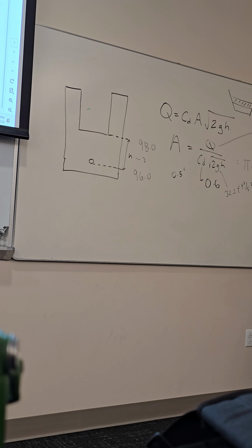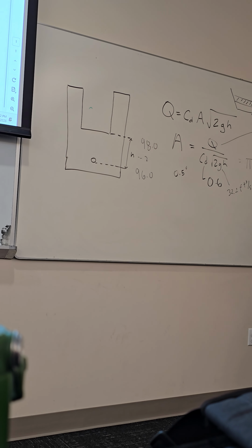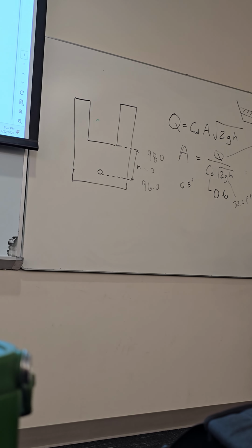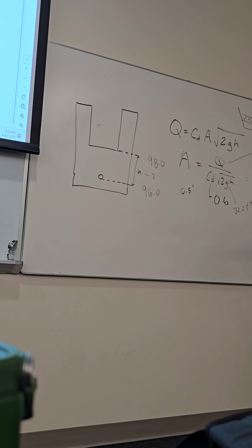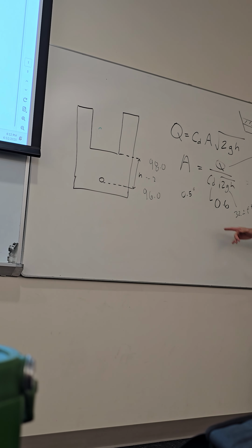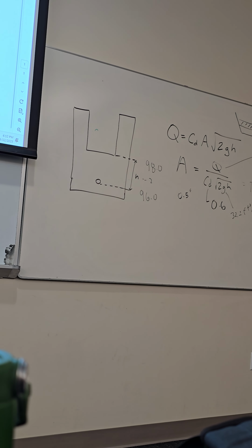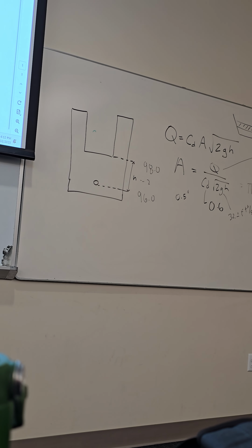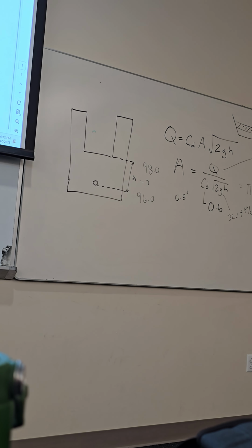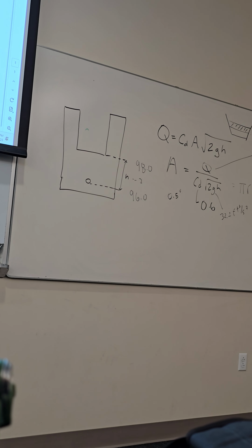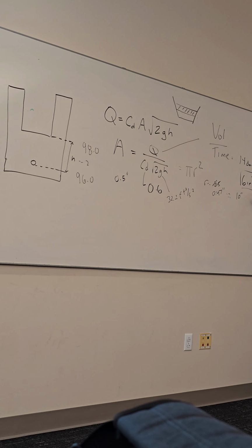It's gonna get clogged, right? So you wanna make it big enough so that you have that factor of safety, because you still wanna be able to vacate the water, okay? So if you calculate something that's that small, you wanna go ahead and use that value, whatever that diameter turns out to be, okay? Now, if you get something that's larger than that, that's fine, okay? But if you get something less than that, you wanna use this number.